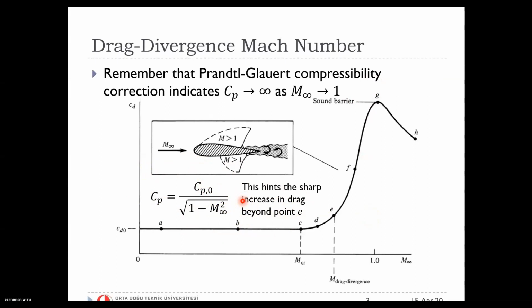Okay, so then what happens as you get close to Mach number 1 here? So at Mach number 1, which is referred to as the sound barrier, you have a peak in drag coefficient, and then as you move to the supersonic flow regime, as you get Mach infinity larger than 1, it starts decreasing again. So then what you need in order to really have a supersonic flight, you really need to have a strong engine that can generate enough thrust to overcome these large values of drag, and particularly at Mach number 1, which we refer to as the sound barrier.